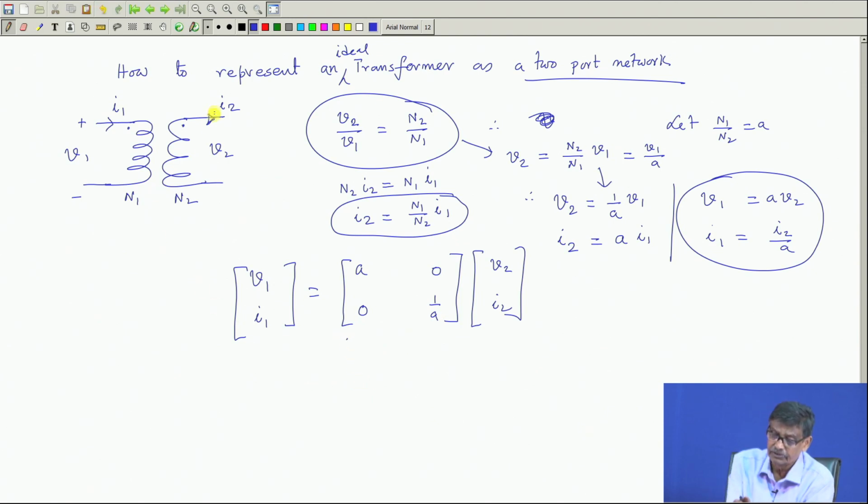So it is also a 2-port network, a 4-terminal 2-port network, not that these two are joined, though even if joined you can. But what I am telling is this is a, this is a. What do you think these parameters are? Is it Z, is it ABCD, is it H parameters? It is ABCD parameters, because I have assumed I2 like this, and input voltage and current are represented in terms of this.